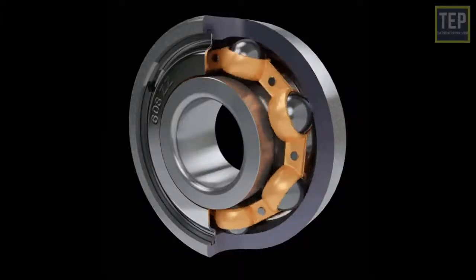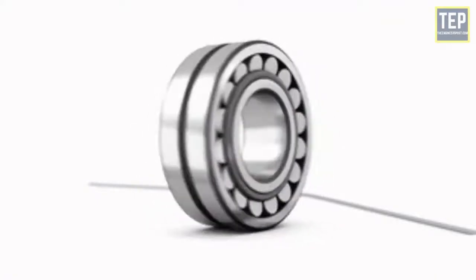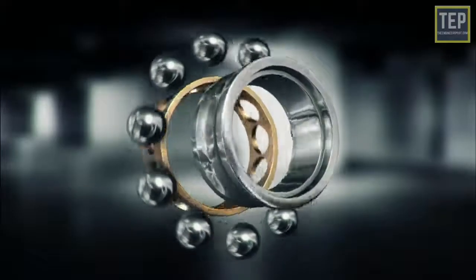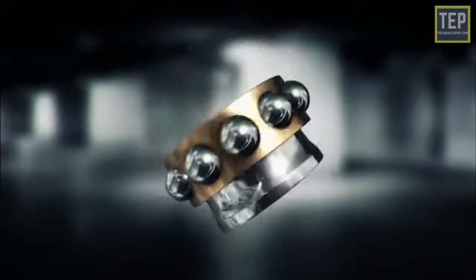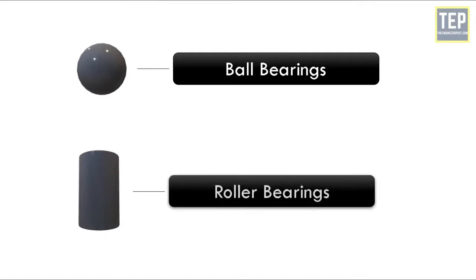These bearings are used to facilitate the free movement of parts in rotational motion. Rolling elements carry the load without much friction, as the sliding friction is replaced with rolling friction. Rolling element bearings can be subdivided into two major types: ball bearings and roller bearings.